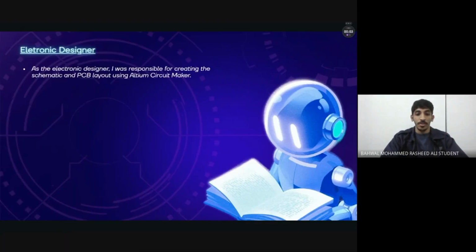As the electronic designer, I was responsible for creating the schematic and PCB layout using LTspice and CircuitMaker. I learned how to choose the right components based on voltage, current, logic type, and package of SMD or DIP. I also learned to route power and control signals like VCC, GND, and logic lines carefully. Using AND gates, I designed simple logic control that responded to button inputs. I made sure that the schematic matched the physical components carefully, using the right footprint.